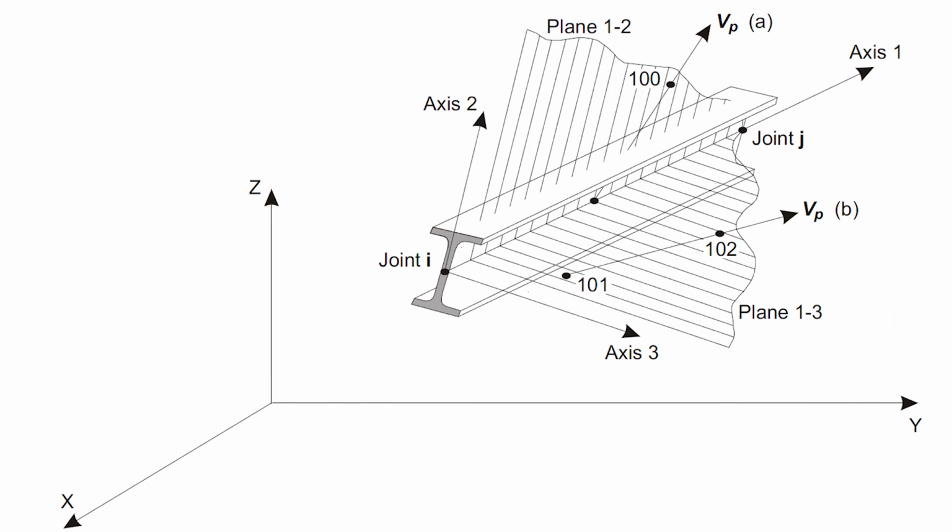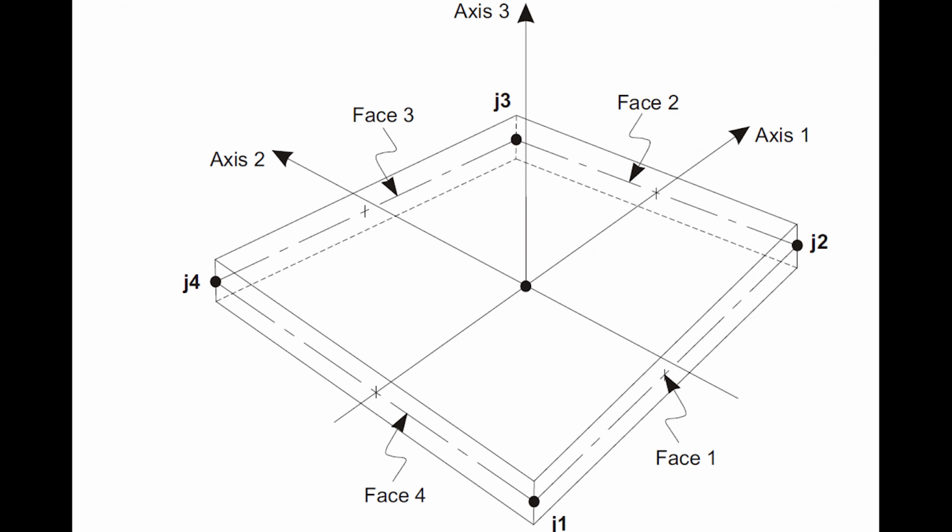For the structural design of a building, it is practical to estimate the structural behavior of beams and columns using line elements, which reduces the number of degrees of freedom required in comparison with the brick element. And the structural behavior of a floor or wall could be estimated using area objects such as shell elements, which reduces a significant number of degrees of freedom required in comparison with the brick element.